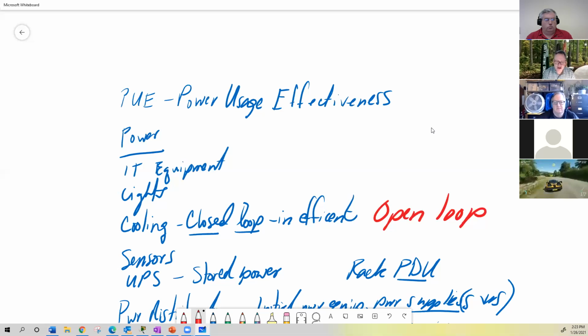The hotter the air, the more airflow to cool it and to extract that heat from the server and the components inside the server. The plenum, yes, is that open area of air, that space in between the drop ceiling or the false ceiling and the next floor or the actual physical ceiling of the data center.